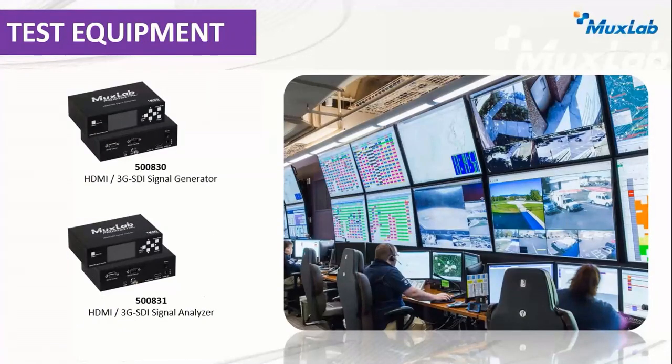And I've got a couple more slides left. This is a testing device, a testing tool that installers can use in the field when they're doing their installation. Often they don't have the TVs or the sources ready when they're doing the wiring. Cabling the infrastructure, basically. This allows you to simulate or to replace the actual source with this generator and replace the TV with this analyzer. These are battery powered with rechargeable lithium-ion batteries. They hold a charge for up to 5 hours, so you can be in the field without power, being able to generate signals, both HDMI and SDI.